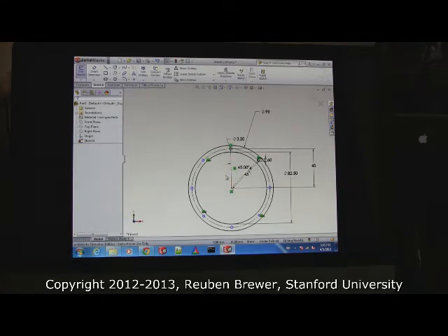Okay. If you did something and you're like, hey, this should be black, this should be constrained, it's probably because the object is still selected, and it's really annoying. There are slightly different shades of blue, but the shade of blue for selected is eerily similar to the unconstrained color. They're confusing. So anytime you think it should be constrained but it's not, hit escape and hope it turns black.